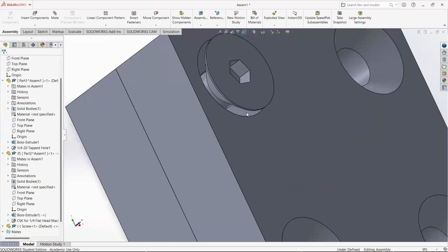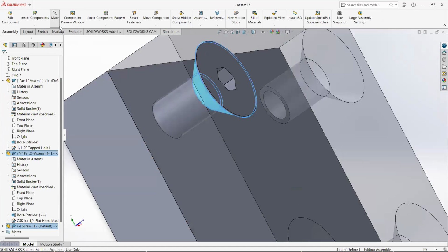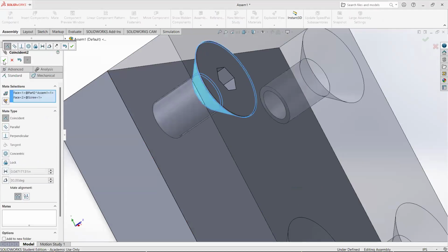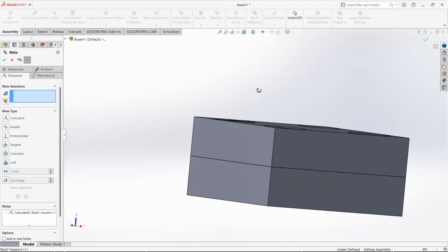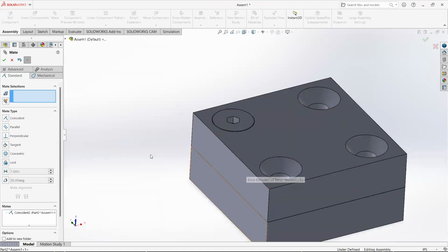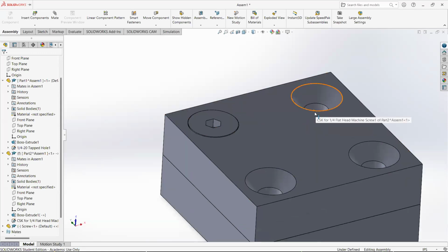now if I attempt to mate my countersink with the bottom of the screw, they should be the same angle, and things are happy. Notice the screw moved into position properly. So I can mix and match, like I said. The top plate and the bottom plate were drawn in context. The screw was brought in and mated the same way that we have in the past with assemblies. So in-context assembly is a quick and easy way to get our parts lined up, without having to flip back and forth between windows, right?